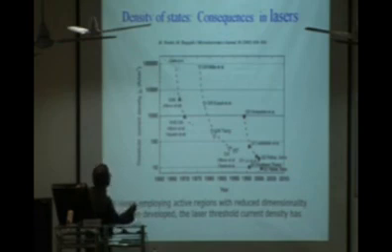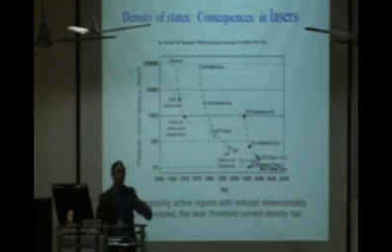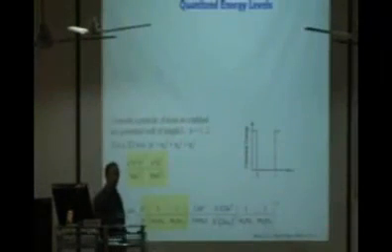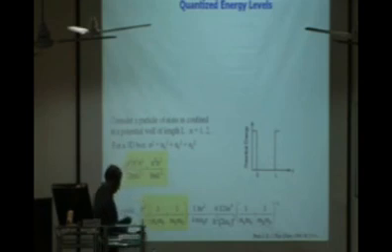And finally, as you said, if you make quantum dots, the density of states now becomes very, very sharp. As the density of states becomes very sharp, the energies are confined within a very small energy level. So basically, the threshold energy for this quantum system becomes very, very low. So people are going nowadays with a threshold current density of less than 1 milliampere per centimeter square or 1 ampere per centimeter square. That means you can drive a laser with a current of about micro to milliampere.